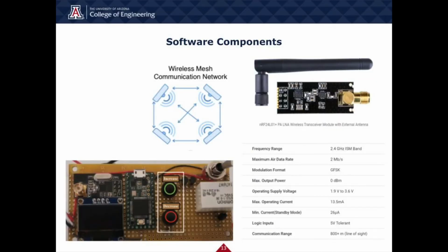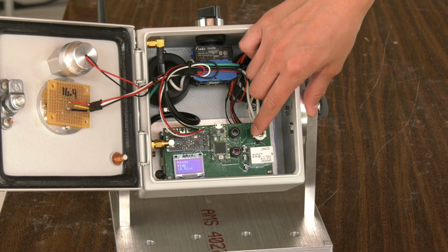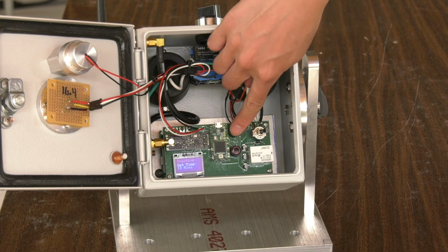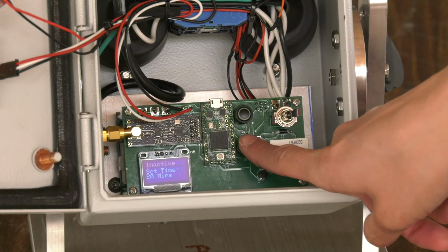Since the jaguar enclosure does not have internet connection that can be used for communication purposes, we implemented a mesh network through the use of radio transceivers. We also implemented an LCD screen and timer to each individual sensor subsystem unit to ensure a proper activation-deactivation period of power input. The timer functionality allows the user to allocate a specific amount of time that each individual activity is activated for and will receive power from the relay.